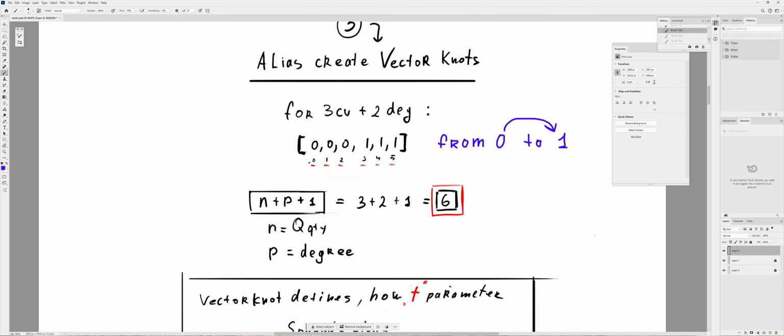So why 3 numbers? Why not 2? Why not 10? Now that's because, as I said, at the core of all of that there is of course a polynomial, and the derivative defines how fluid the curve will be, how much it can bend, the amount of torsion it may have, its fluidity. So to force the curve to start from the point 0, we need to be sure that the derivatives are equal, they are the same, at the given point.